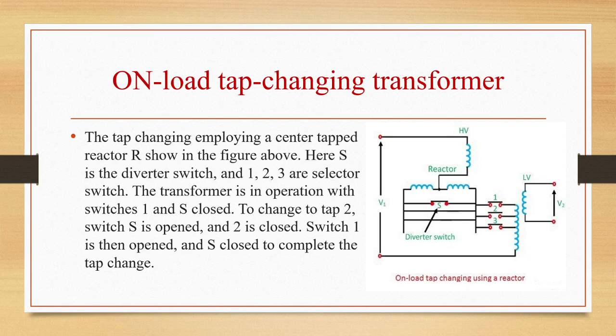Now we are going to see its working. Tap changing employing a center tapped reactor as shown in the figure. Here this is a center tapped reactor. S is here a diverter switch, and 1, 2, 3 are the selector switches.